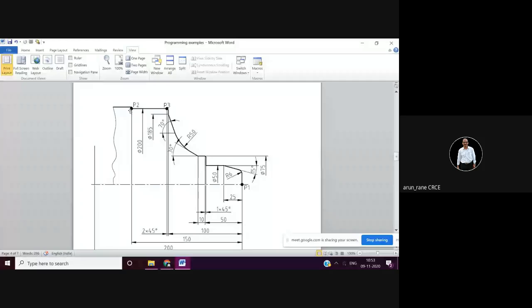And what is going to happen here? I hope this block is clear. That is, you are going 90 degree and you are going till point x200, and here you are doing a taper, chamfer of 2 mm, and then you go straight 150 down. Okay, that is up to this point. So this will be z minus 150 and the angle will be 180. So this is turning like this. Angle will be 180. That is this.